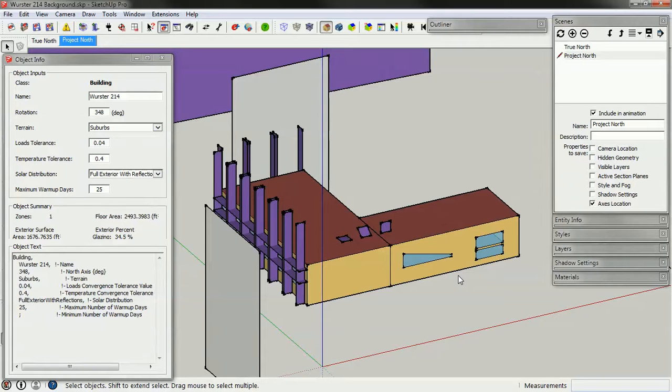But you do want to make sure that you get appropriate numbers of appropriate orientations that are best representative of your building, as well as representative of your programmatic areas. So, for instance, if you have a kitchen and a bedroom, model that as one zone, and then we'll have to average the loads later.